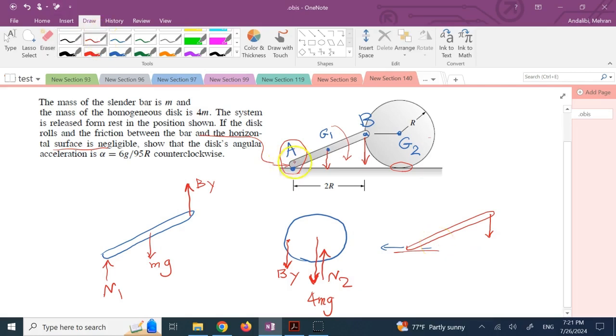Okay, that's right. And when this point moves to the left, the centroid, since this is the center point of the points A and B, the velocity of it is going to be the average of these two. So this is like V of A, this is kind of like V of B. So G1 is going to be the average of the two, so it's going to have some motion to the left, some motion downward, so G1 is probably going to go like this. And so the whole object, as you can see, has some left motion in general, right? The centroid of the object has the tendency to take the object a little bit to the left.